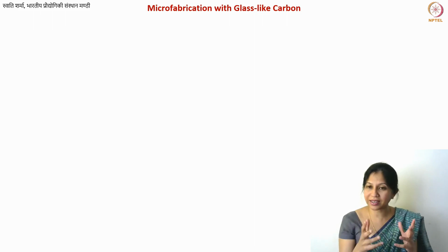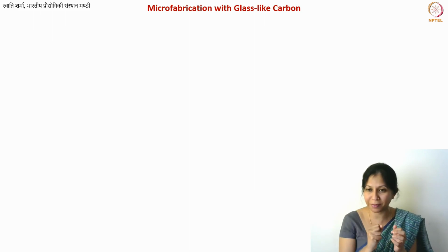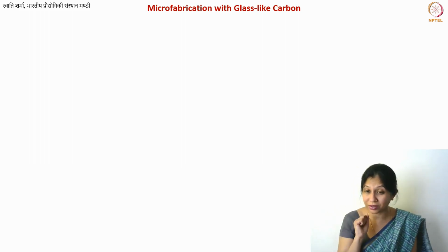We discussed this in detail: if you have very large structures made of polymers and then you convert them into carbon, these thick structures may end up having some bubbles trapped inside them, in the core of the material. These bubbles are caused by the byproducts, the tar-like materials and synthetic gases that are released during the pyrolysis of the polymer. And since the structure is too big, they are not able to anneal out in an efficient manner.